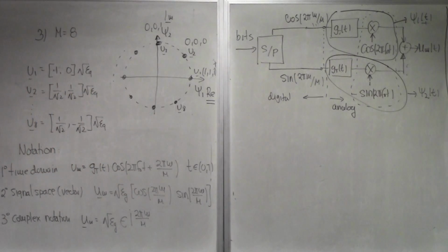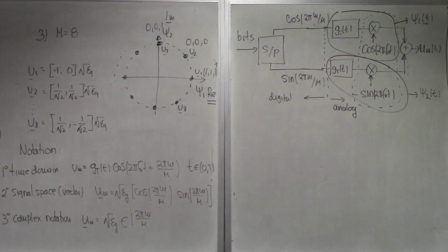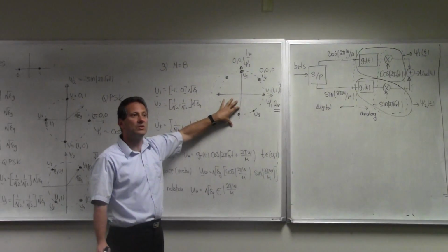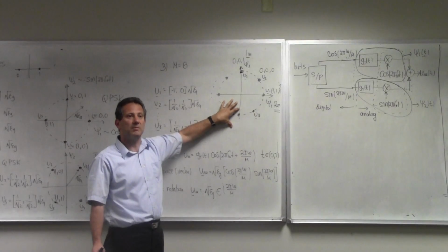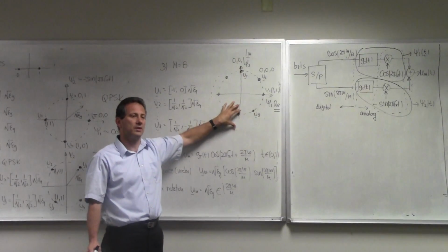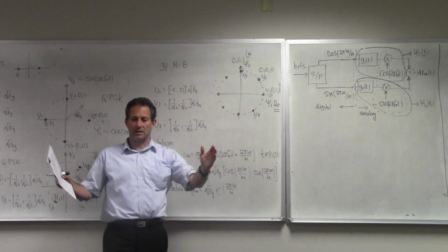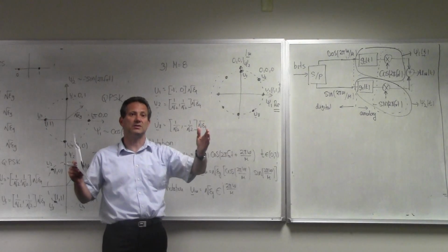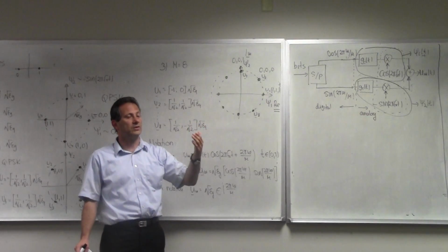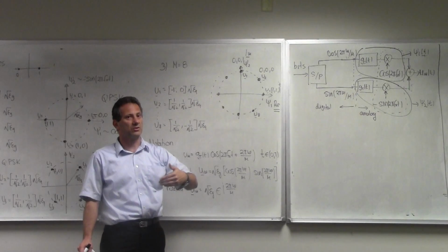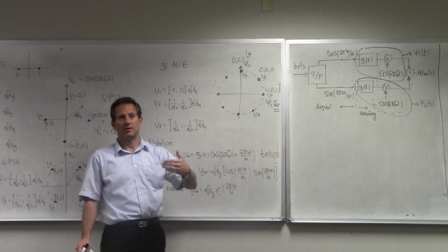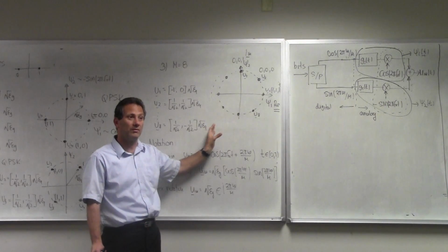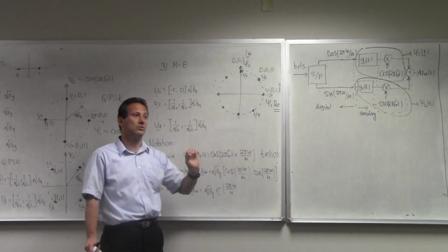And just the last thing to say about PSK, I already said it, but this is something to remember: PSK puts all of your symbols on the same unit circle. That means they all have the same energy. Now, why is that important? Think about a signal. This signal has a certain energy and lasts for the duration of T, the signaling period. So the ratio of the signal energy to the signaling period stays constant. What is this ratio? Energy over time. Power, beautiful. So the power of a PSK signal stays constant over time.